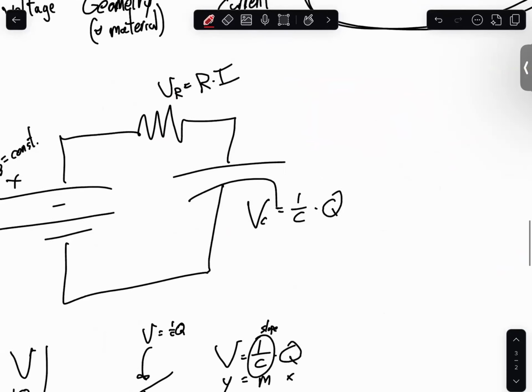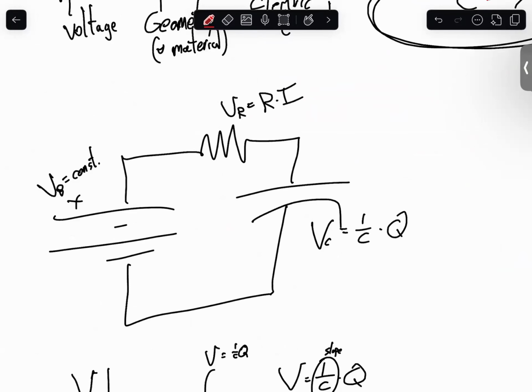I would like to talk about what you're going to do in lab next week to prepare you, as I promised in the email. Let's talk about what happens if we actually charge the capacitor with a battery. You can't actually connect the battery directly to a capacitor. If you try, the wires or the internal resistance of the battery will act like a resistor. In lab, you can use an external physical resistor, so you don't have to measure those. Also, if you use a fresh enough battery with big enough capacity, you might be able to get something to melt or catch fire. I don't think the 1.5 volt batteries are going to do that, but let's not try.